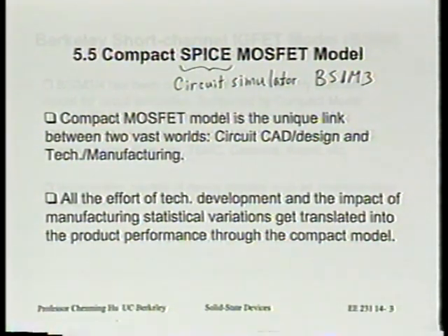Now, in order for the simulator to work, the simulator has to have a way of representing the transistor behavior, right? And you can see if you really want to represent a transistor very accurately, you have to put in a lot of physics. So that's something not really in the domain of a person who designed a simulator, more in the expertise domain of a person who knows a lot about transistor physics. Right? So these models then are put into the SPICE engine or work with SPICE engines for circuit simulation. Do you see what I mean by that?